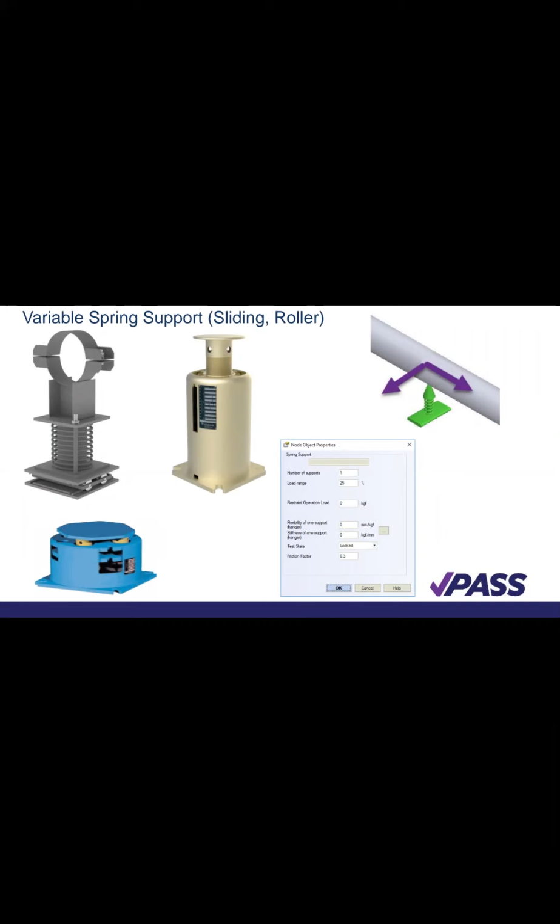When the support has a spring, it compresses and it also goes into tension. So if the load on the spring is much, it can compress. Then when that load is released, it will get back to its state. So that's why we call it variable, and we can reduce or increase the length of such support. And when a load is affixed on your pipe,